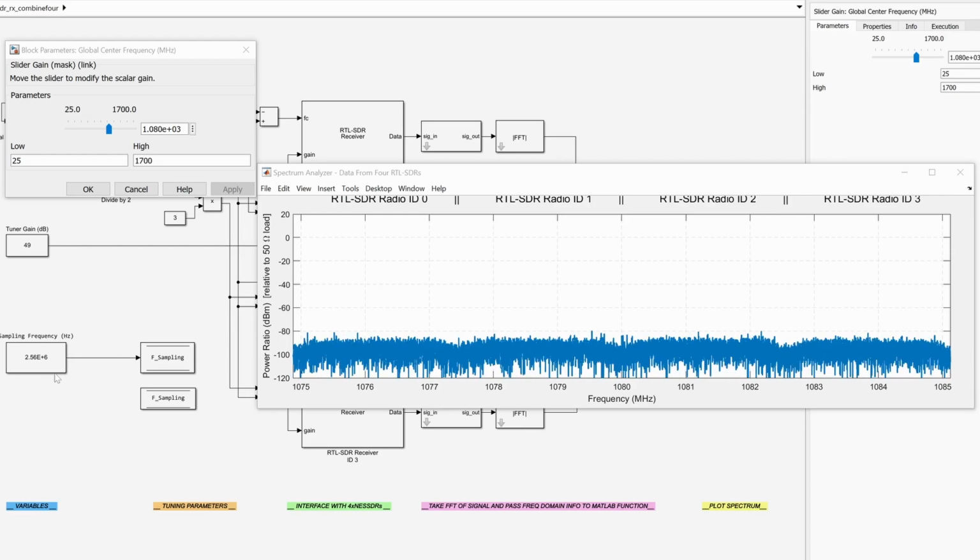Remember that you still won't be able to decode information of wideband signals that way because the 4 SDRs are not clock synced in this case. They each have their own TCXO reference. But you will be able to do that though if you can tie all reference inputs to one source of 28.8 megahertz in this case.